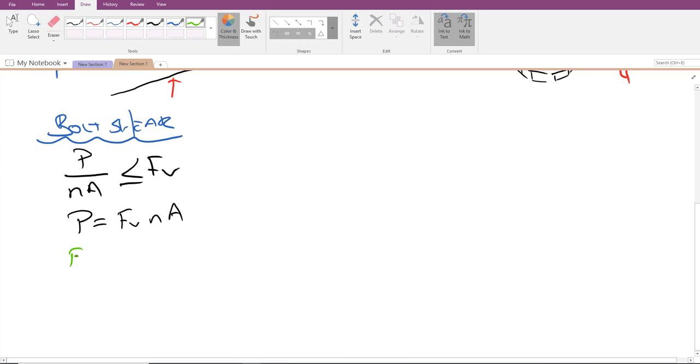If we go to table 10.1, and look up what the shear stress value is for these bolts. It varies for bolts. For the A325X bolts, the shear stress value is equal to 30 KSI. Again, you'll see that in table 10.1.